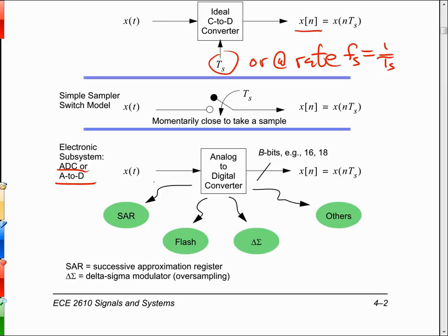So in an audio bandwidth, you can handle that 64 times oversampling, but if you're working in a radio receiver front end, the 64x oversampling is going to put you into the gigasamples, and that's going to require very powerful post-processing. It's going to use a lot of current, and so on.